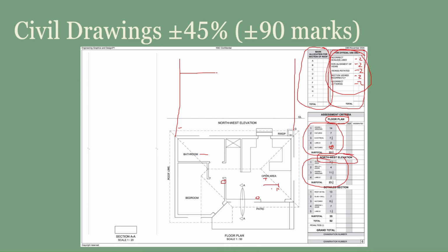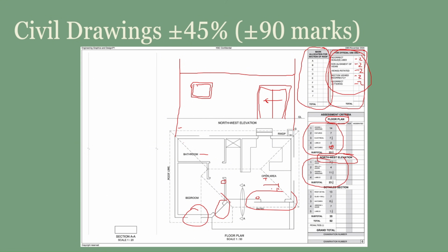You are going to apply it here, and you're going to project this window, that door, and the sliding door up to that view, and you need to put in detailed information to the sliding door with an arrow if there's a sliding door, and if there's a window, you will need to put the detailed information in of a window, which you can see the frame as well as the opening of that window with a window sill.